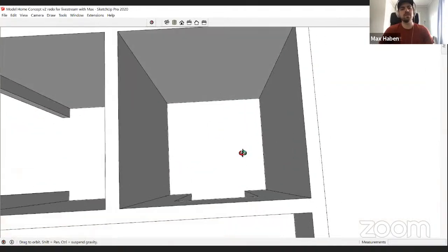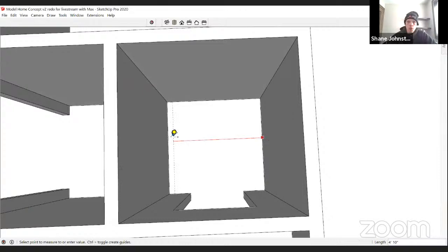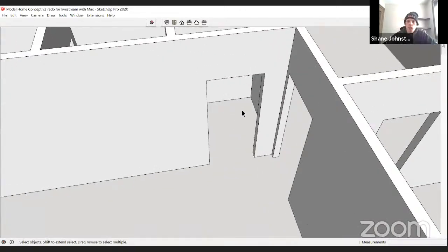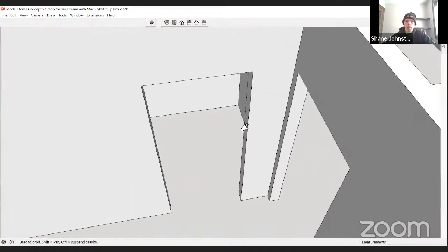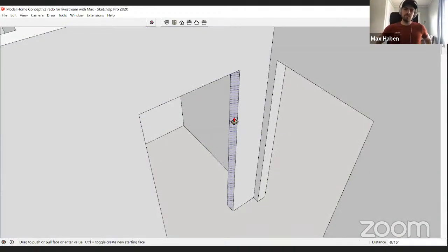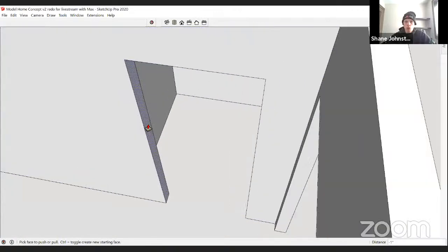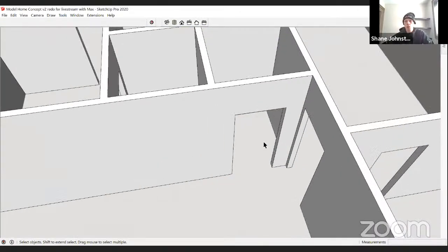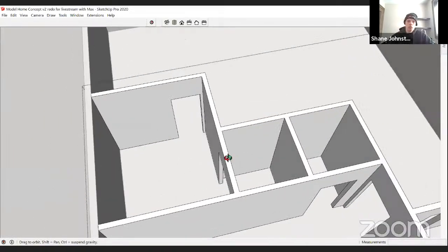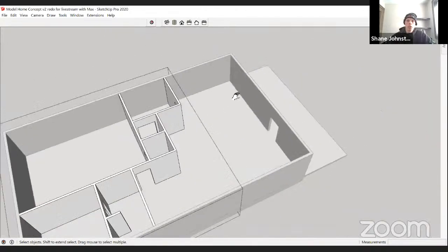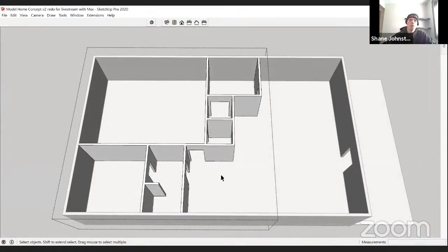Yeah, so gotcha. I think we will probably shrink this one down a bit too. Makes sense. So that's your water heater, your furnace, maybe a bit of storage. I like to make these doorways a little bigger. Say you need to replace a furnace or water heater, get tools and the water heater in and out of there. Getting yourself some elbow room in there is pretty handy. Makes sense.